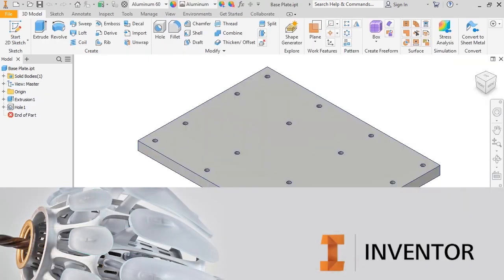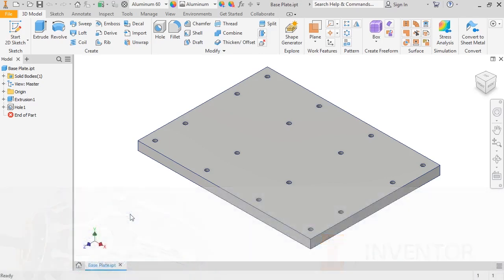To make complicated assemblies a bit easier to work with, Inventor allows you to create something called subassemblies, which are created when you insert an existing assembly into another assembly. Once inserted, they can be constrained and positioned just like parts. So, in this lesson, I'll create a new assembly using this base plate and then add the pin, wheel, and bracket assembly to show you how to work with subassemblies.